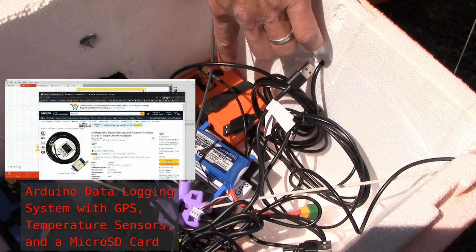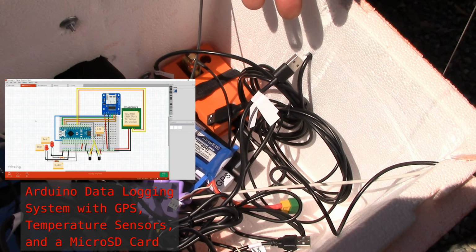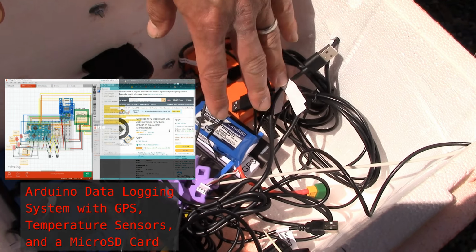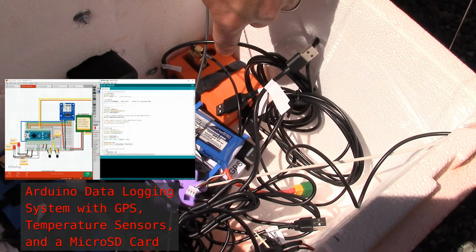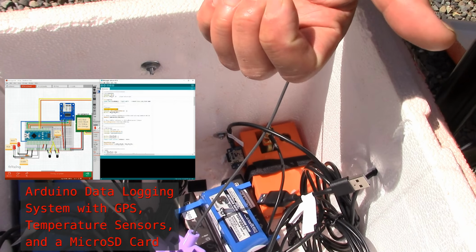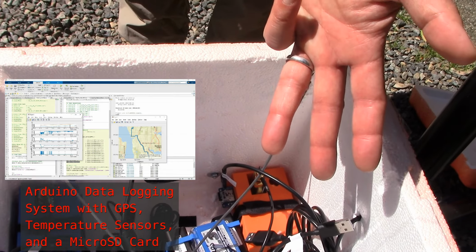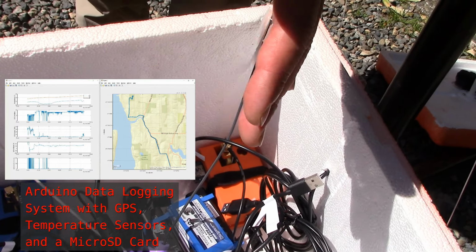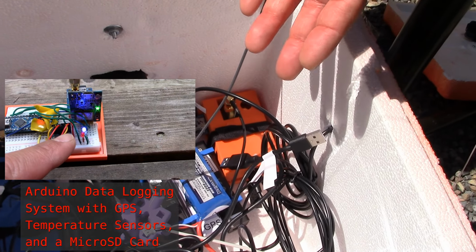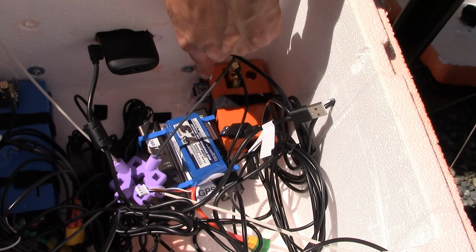This one is a completely separate redundant tracking system, which has a GPS antenna hooked up to it, and it is hooked up to our 2 thermocouples, one external and another completely separate independent internal one. All it is in charge of doing is logging the position, namely the latitude, longitude, altitude, as well as other GPS information like the number of satellites visible, HDOP, and also logging those 2 temperature sensor measurements. It's just going to do this at a much higher data rate, and store all that information on board on a micro SD card.